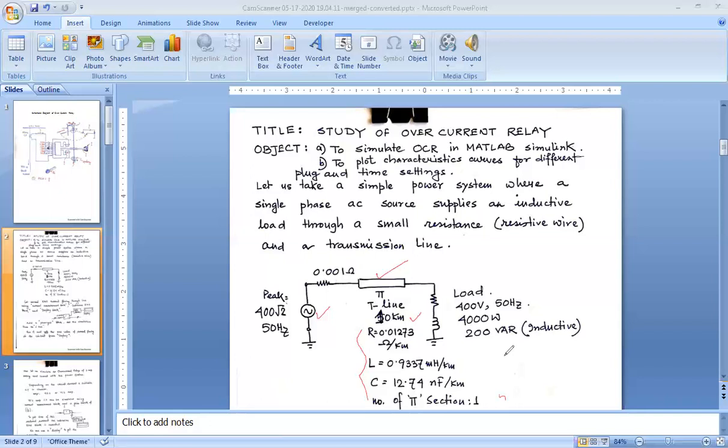And another way to get the RMS value is we can also connect an RMS calculating block available in the library, which is known as the continuous RMS, and it is directly connected with the display. So all are available in the library, so you can get this RMS value directly.